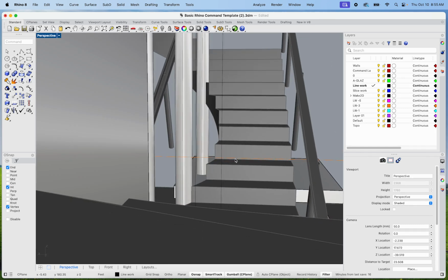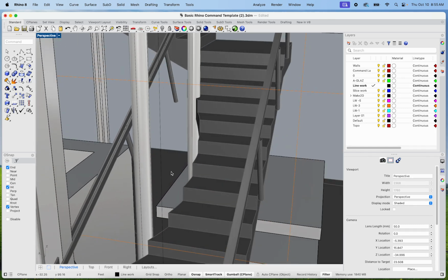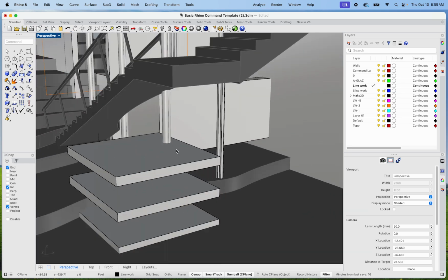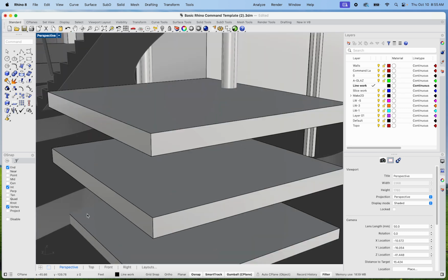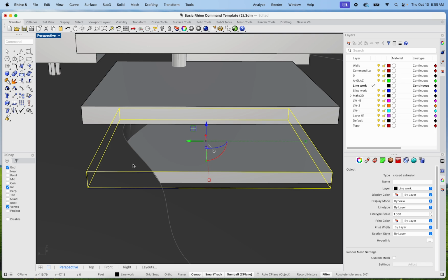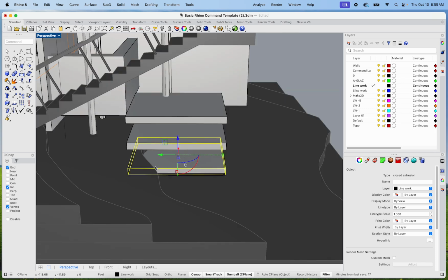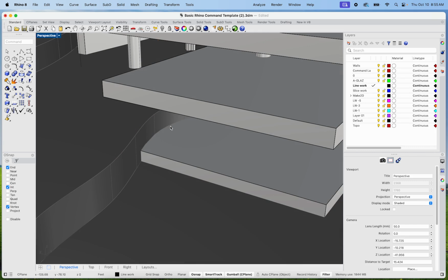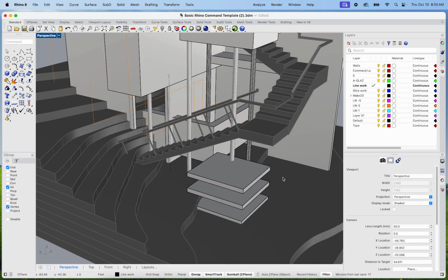So as you can see, I had to cut away from the stairs at some point. Please don't just randomly cut your stairs. But that's looking good so far. And you kind of have to stare at these pieces a little bit and go, okay, what's going to have to happen for this? Do I need to chop that away? Is that something that I could just do in the physical life, right? I mean, because that's something I could just line up to the cardboard and cut it off manually with an X-Acto blade. However, if I wanted to be more specific, I could Boolean difference these two pieces. That way I can get an exact object for that piece. And that'll make sense in this next portion.